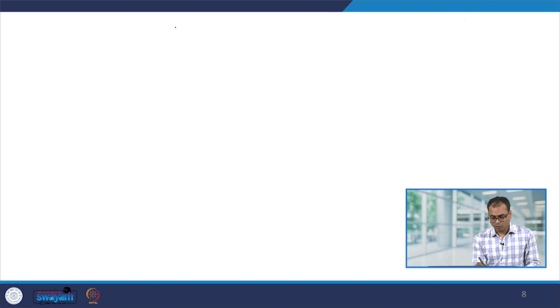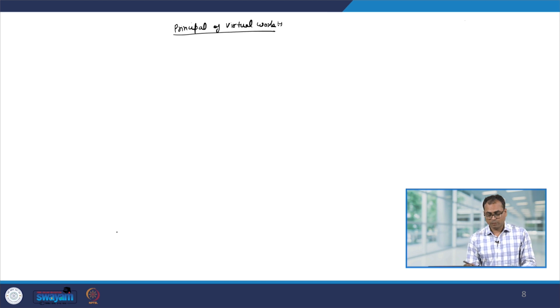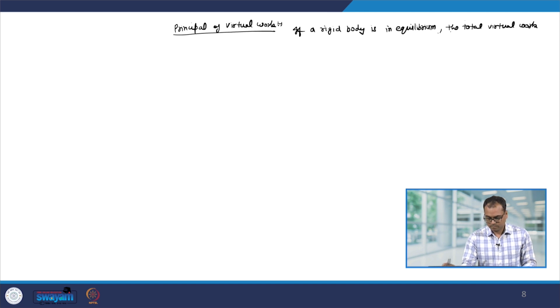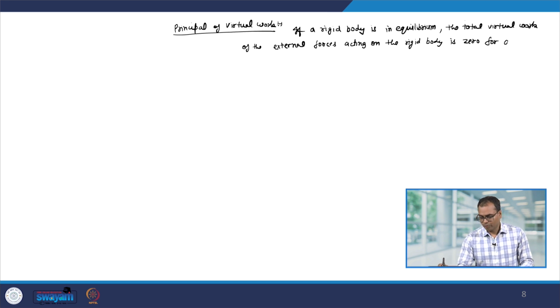We next studied the principle of virtual work. And the statement of the principle of virtual work is following: if a rigid body is in equilibrium, then the total virtual work of the external forces acting on the rigid body is 0 for any virtual displacement of the body.